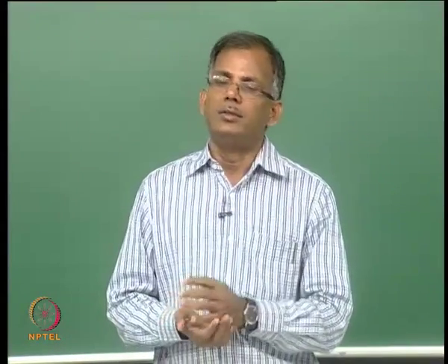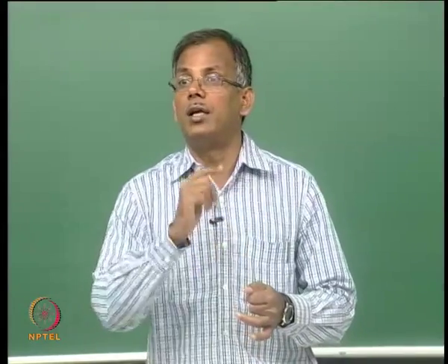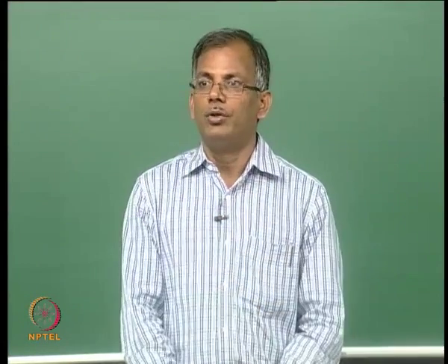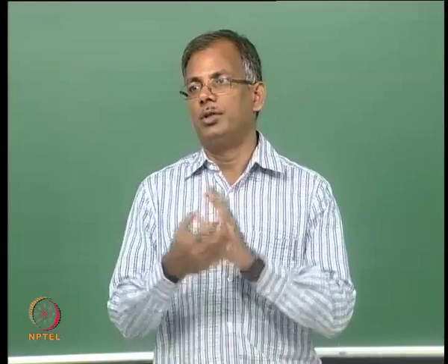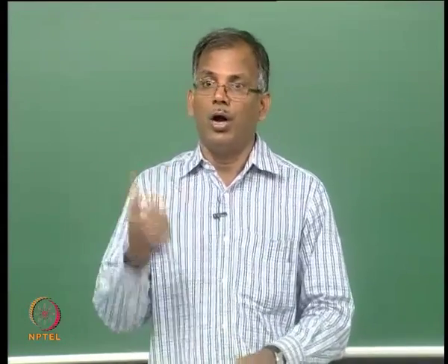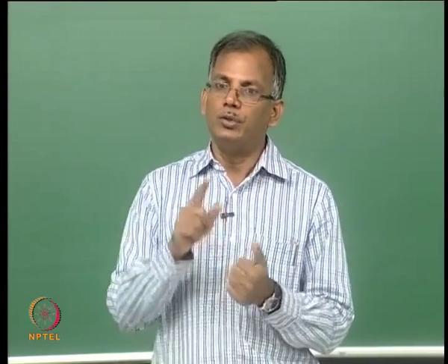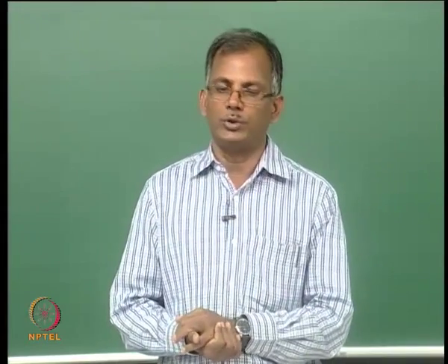So, how do you decide when to restart the loading process, because every time you unload, you bring the load to 0 and then stack up to the next increment. For example, first at 200 tons you bring it to 0, which means you have to take out the load and load it again to 400 tons. As soon as you see the displacement relationship going flat, you can start, but if the rate is still outside the limit, you cannot. When displacement is still happening, you cannot do an unloading process.